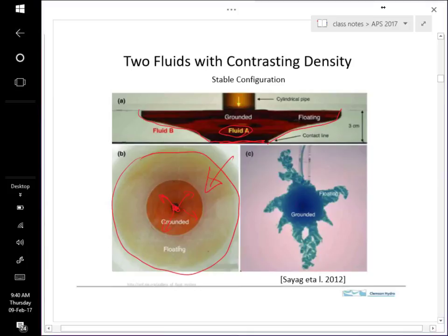And then if you change the fluid, probably what's happening here is the viscosity is reduced, and you have a situation where you inject, and now you have this unstable pattern where the fluid, instead of spreading out as a nice uniform front, is coming out in these fingers. Okay, so this is an example of unstable displacement, still of a light fluid displacing a denser fluid, but when you change the viscosity contrast, you go from a stable over here to unstable.